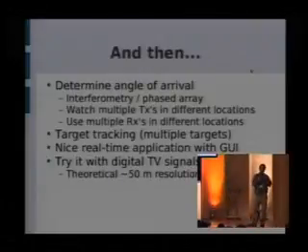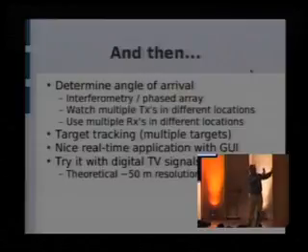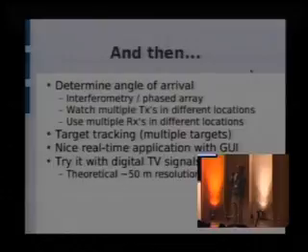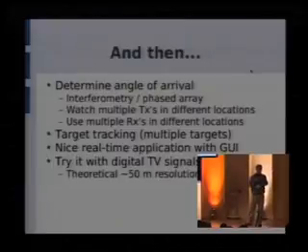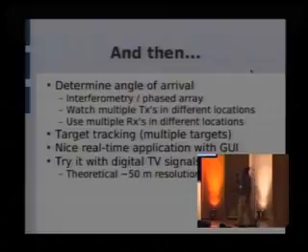What's cool about those is that even using just 4 of them, you can steer the beam, or you can steer a null. You can either focus over here, or you can steer this part that's notched out. So maybe what we want to try is steering the notch towards the main transmitter. But the theory only gives us about a 10 dB attenuation towards the transmitter, so we may need to combine the big screen behind it and the phased array antenna. There are a couple other ways we could go, doing some more analog tricks, but we're going to try to do it without getting crazy about that.